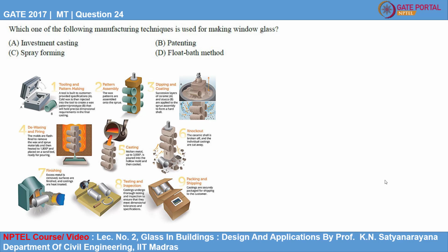It is a heat treatment of steel wire. We heat the steel wire up to 870 to 950 degrees Celsius, and then cool it to 450 to 550 in salt or lead melt. Then the wire undergoes isothermal holding and further cooling in air or in water. It is used to obtain a thin plate ferrite carbide microstructure, and the purpose of patenting is to improve the ductility of the metal. So generally before drawing the wire, it is patented.